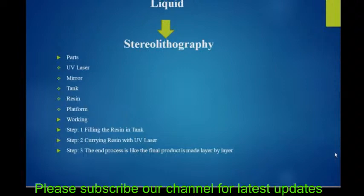If you want rough use, use FDM, because it is a DIY kind of printer, whereas the resin-based printer is high in price, the machine itself as well as the raw material. You switch on the machine only for important purposes. The parts of the machine are the UV laser, mirror, tank, resin, and the platform. The platform is where the model gets printed. In the working, once the resin is filled, the build platform submerges inside the resin. Once the UV laser is projected with the design, it starts producing the model layer by layer.